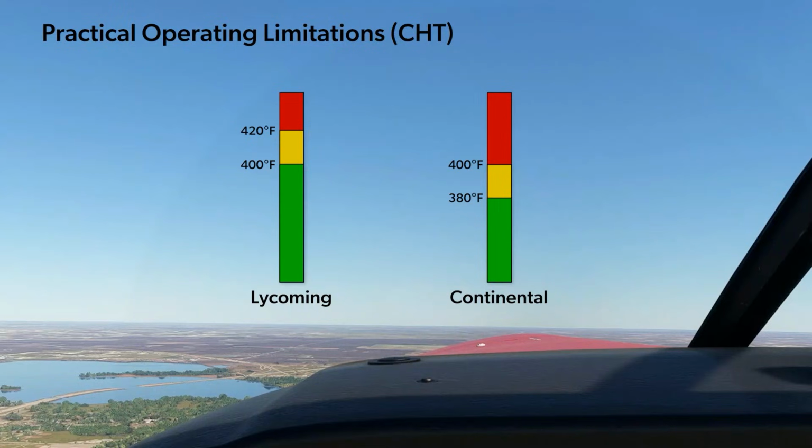The trade-off in doing that is performance. Like I could get a little more performance out of that engine if I could lean it a bit. Trade-off is economy, but temperature cooling, not abusing the engine is much more important at that stage. And the trade-off in performance just doesn't matter all that much to me in Wisconsin at low elevation in a plane that already has a bit of extra horsepower to begin with. So you're always thinking in terms of these compromises and trade-offs and what's most important and what is your goal in a phase of flight.